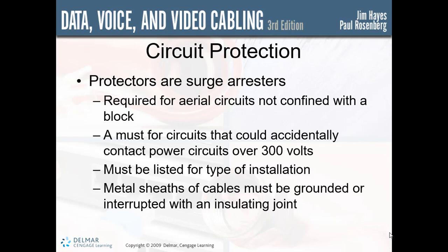And then if they're going to be above roofs, communication conductors must have the following clearances. Flat roofs, they have to be 8 feet. Garages and other auxiliary buildings, there are no specifications required. Overhangs, where no more than 4 feet of communication cable will run over the area, 18 inches. Where the roof slope is a 4-inch rise for every 12 inches horizontally, 3 feet.